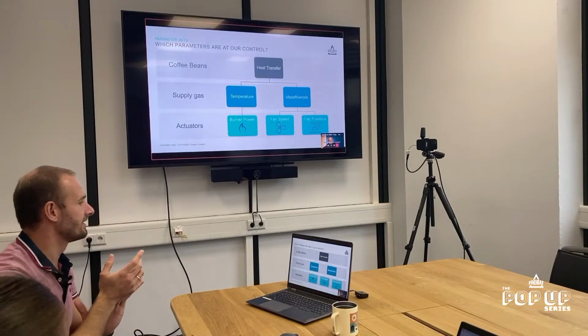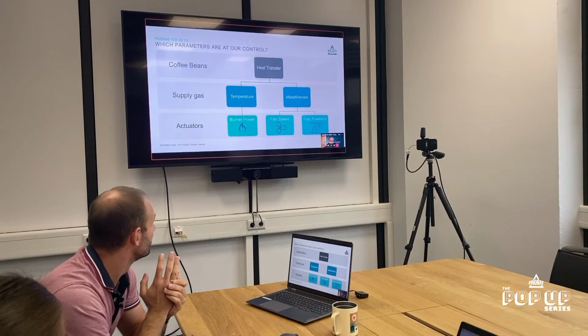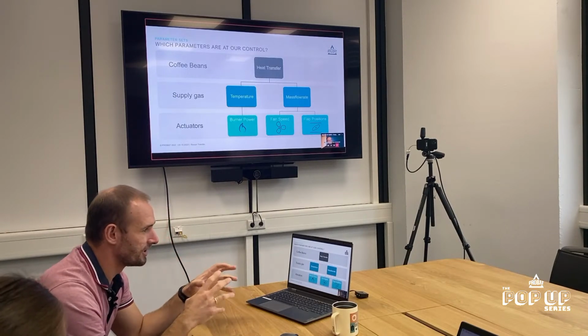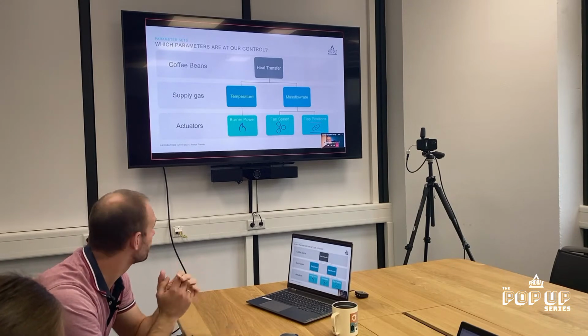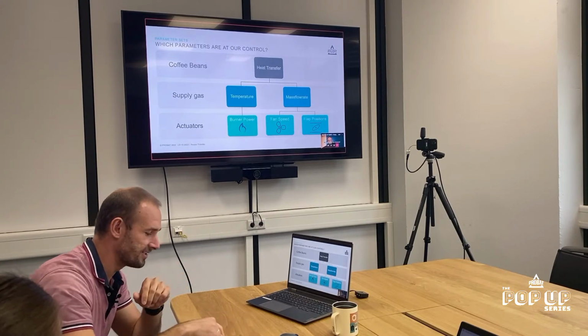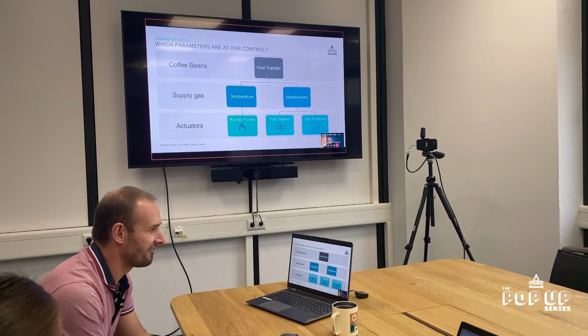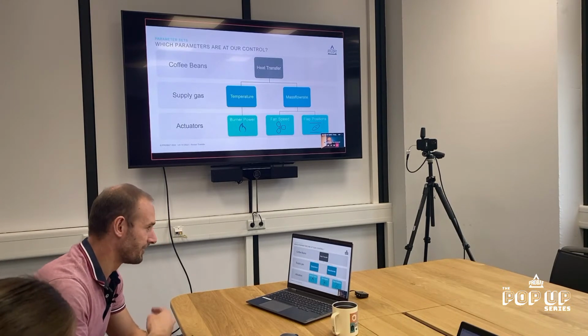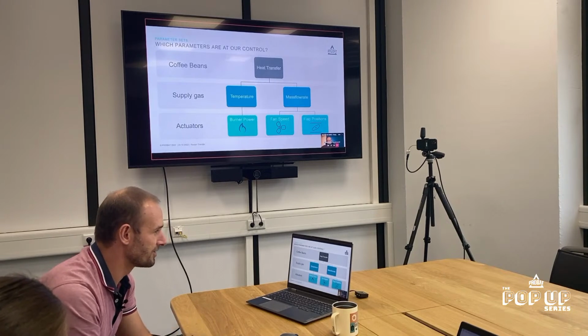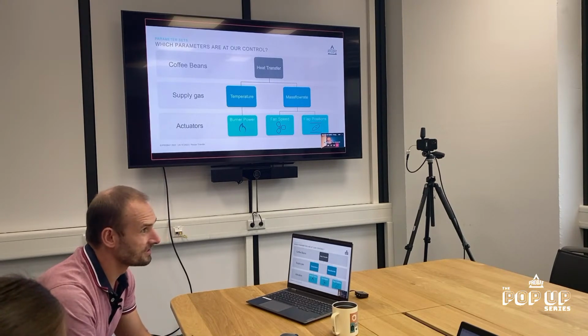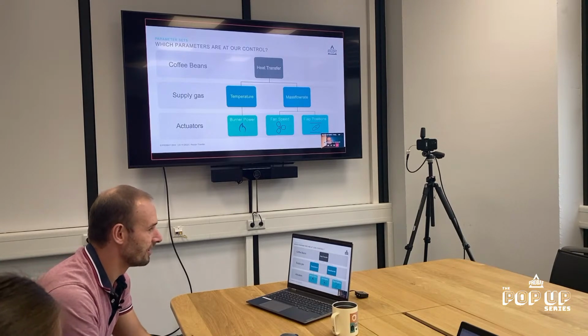And that's why we want to go to a variable which is independent of all those variables, and that is the energy transfer. So if we look back at this graph again, we talked about temperature and mass flow rate and how we need to exchange them between the two to stay on an isocline, on a line of same values. But then you still have the problem of fan speed and flap positions, because you have 3 actuators and you just have 2 variables you want to control. So you again need some sort of modeling to find out how that works.